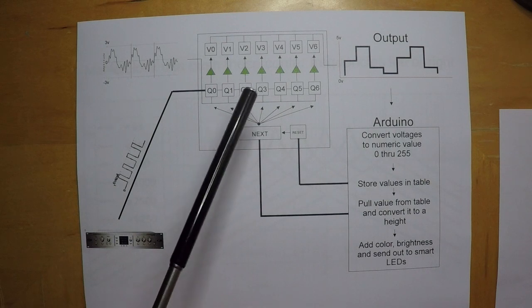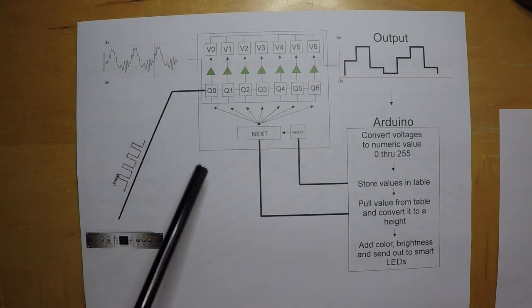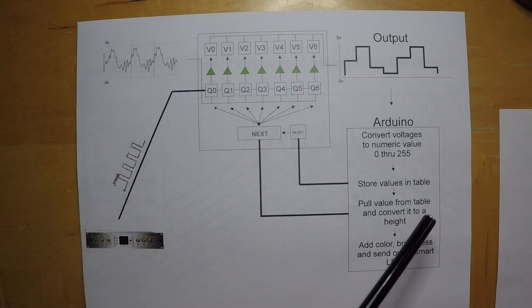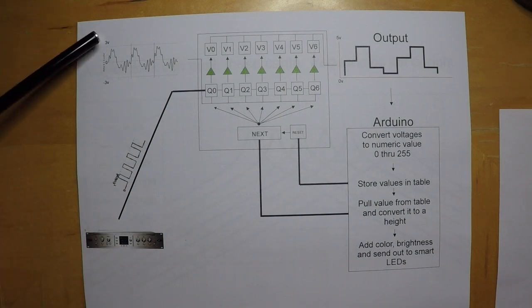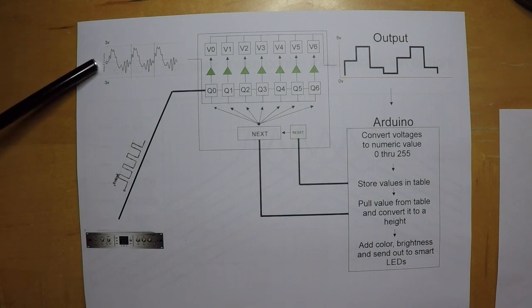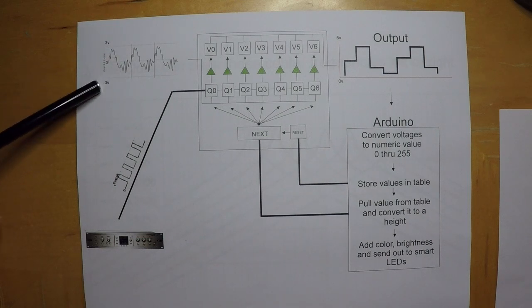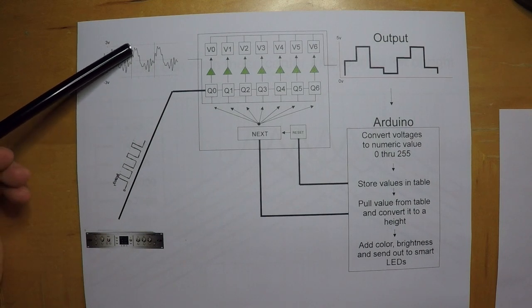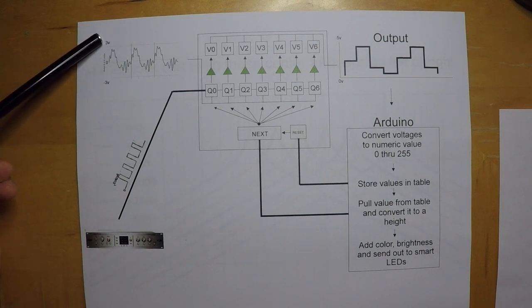This chip, the slicer chip, is kind of a buffer too, because if you look at the voltages that you would see at a line level output from, say, a receiver that you're feeding into this chip, it is crossing from 3 volts past 0 down to possibly negative 3 volts, and back up over past 0 to positive 3 volts.